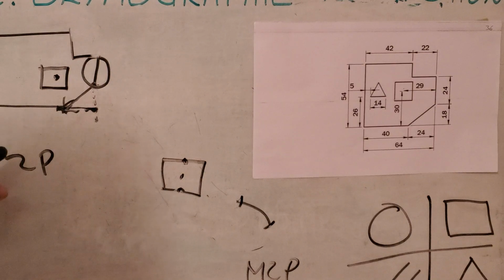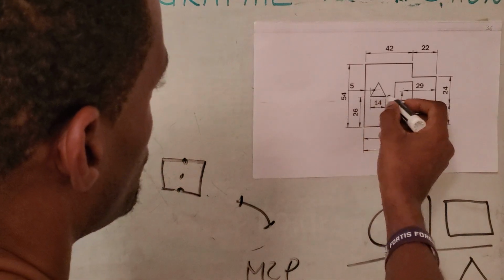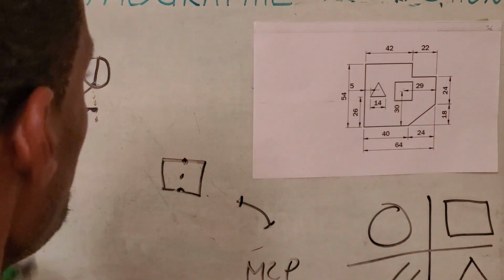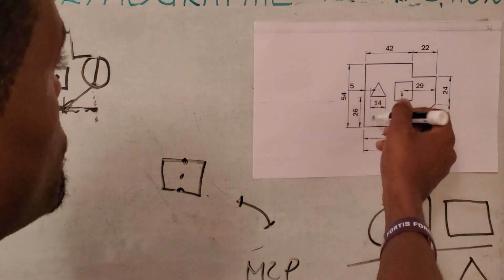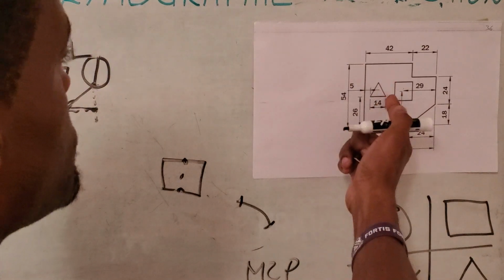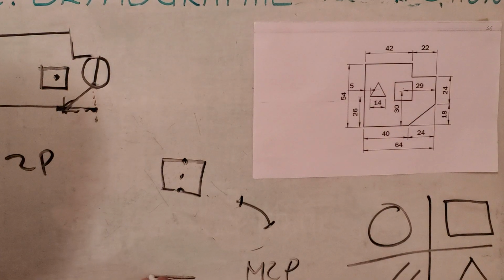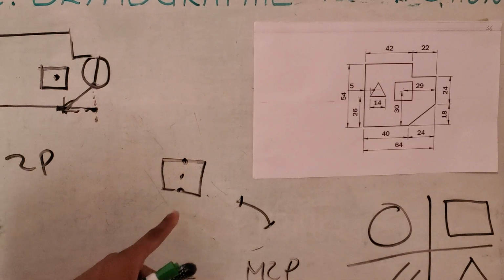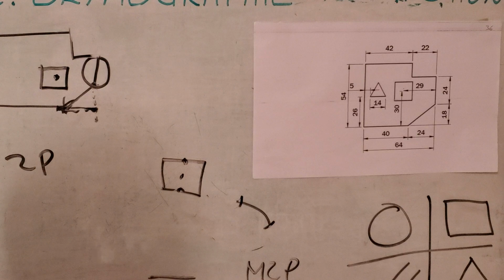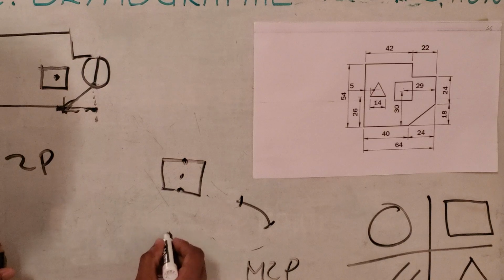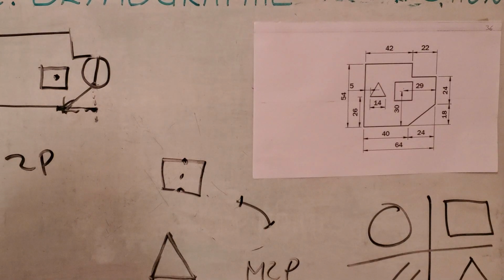Now, the next step is to draw this triangle right here. It is an equilateral triangle, and the base of it is 14. So first I would draw a line, 14. Then I go to polygon, choose 3 sides, then edge. With edge, you click here, and it will generate a triangle like that. So we draw this outside the figure, then move it into the figure.